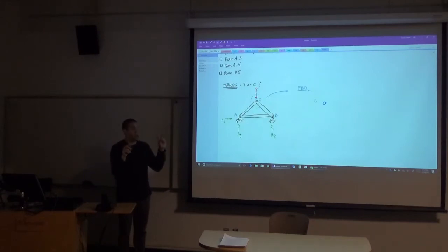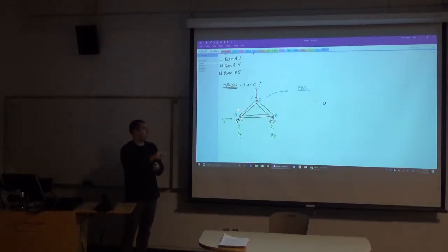That's the definition of what we call a two-force member. And again, it's a little bit of a misnomer. When we say two-force member, we just mean there's a force at this end and a force at that end. They're equal and opposite. But really, there's only one unknown as far as the force in that member goes, because we know that the direction of the force has to be in line with the member itself. The only unknown that we have is the magnitude.